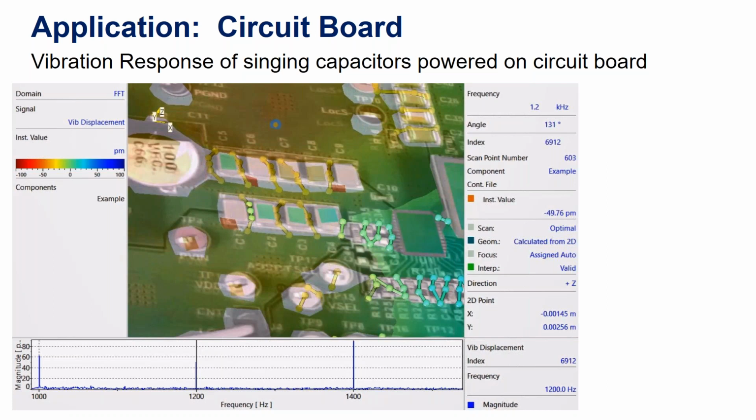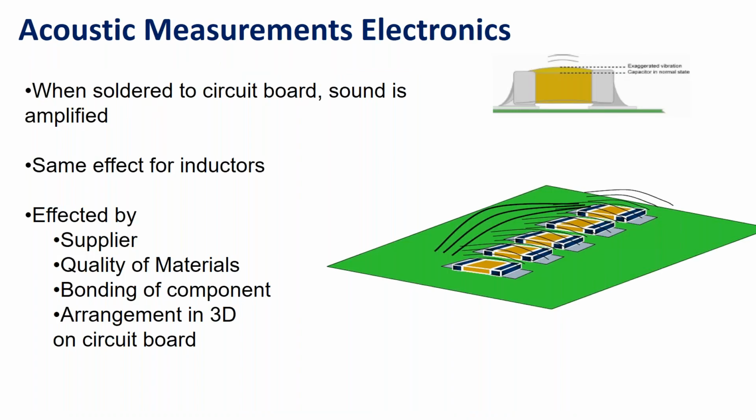So in this case, this was audible. Once you get above 5 or 10 dBs, then you can actually hear that. It becomes a buzzing sound, and that becomes a problem. This is true with multi-layer ceramic capacitors. Once you push current through them, it creates a piezo effect that causes them to vibrate. That vibration at some level can become audible and become a buzzing sound that is unwanted, and you want to troubleshoot and try and minimize or reduce. So this becomes an application where we have singing capacitors.